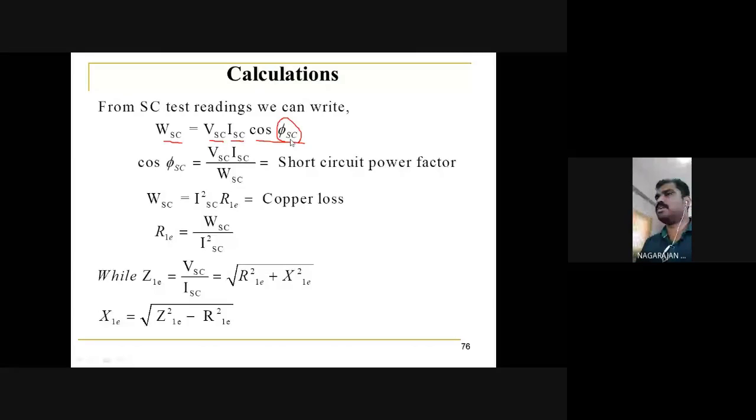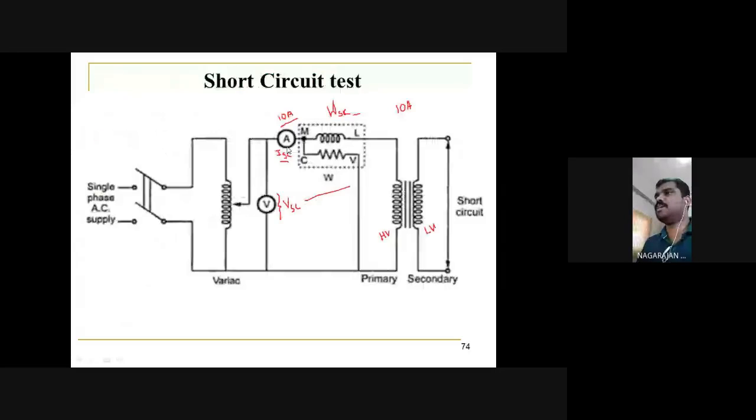So here you are taking three different values. 10 amperes is the full load rated current. If you want to perform this test for half load, what will you do? I have given the rated value as 10 amperes. Rated means, for any electrical machine, they give nameplate details containing rated voltage, rated current, and rated power. If it is a rotating machine, they will give rated speed as well. How will you define rated values, and how will you define half of the rated value?